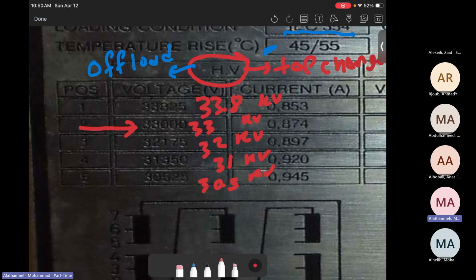How do we decrease the voltage? By decreasing the tap changer settings. We need to decrease the voltage because with a light load we have a capacitive impact. And if we have heavy load conditions, there will be a lot of reactive power consumption. That consumption of reactive power will decrease the voltage, and once the voltage decreases, we need to increase it using the tap changer.